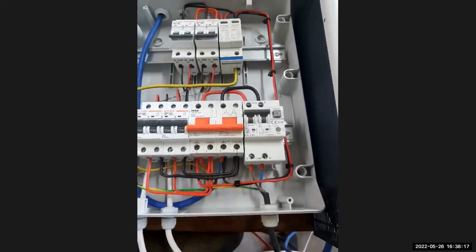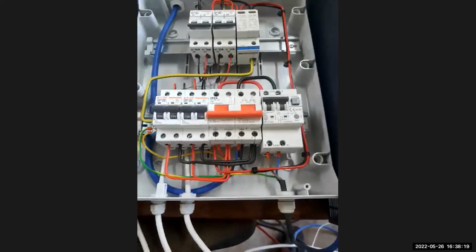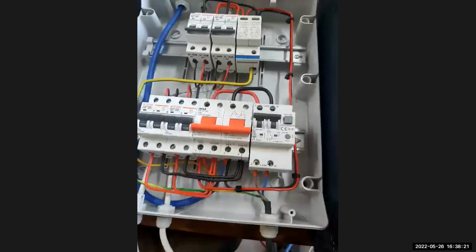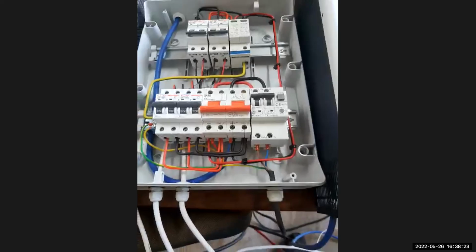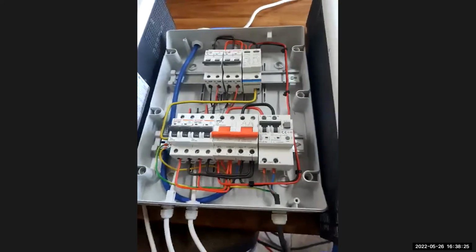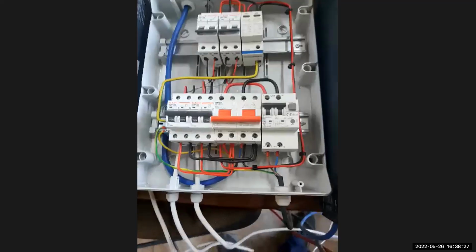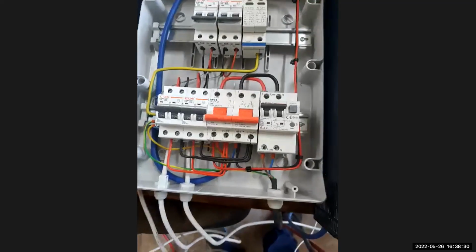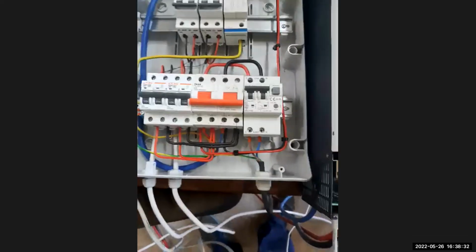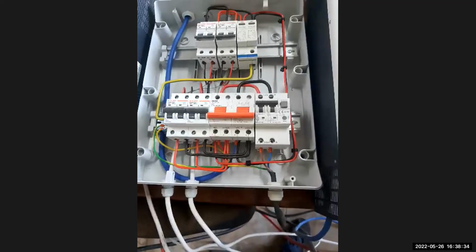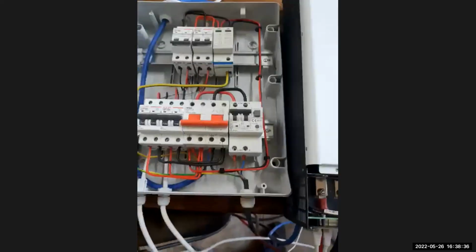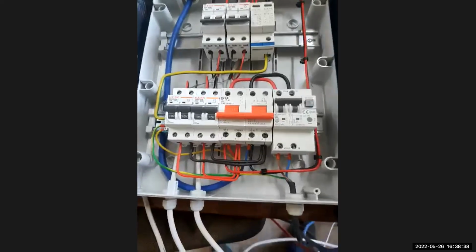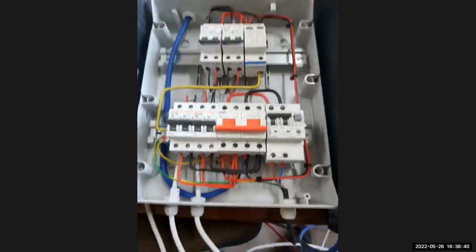If you have a system of 3 or 4 or 5 inverters. If you only have 2 inverters, it is 1 and 2. This small dip switch tells my inverters the position of each inverter. So the inverters only want to know which is my first and my last inverter in the communication chain, and from there on they will be happy.